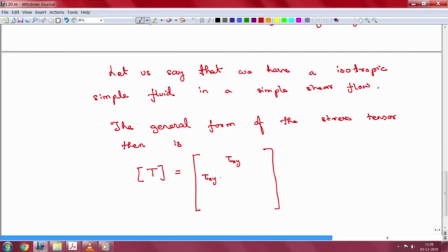So these are going to be there, and the question is what is going to be in these two positions. Now if this was just a Newtonian fluid, you will only have the pressure terms contributing to the normal stresses here, and they would be equal in that case. But here in the more general case, you can have pressure, you can have normal stresses that are going to develop in these directions, and since this is basically a 2-dimensional flow, your other terms are basically 0.